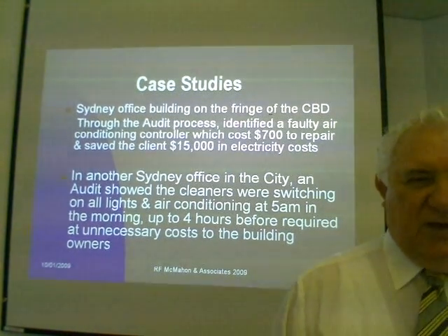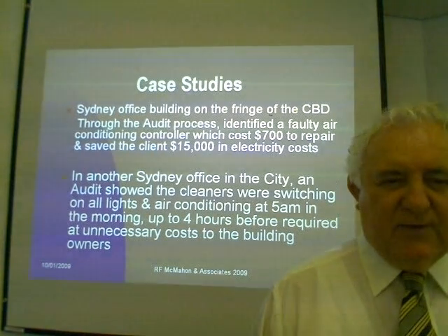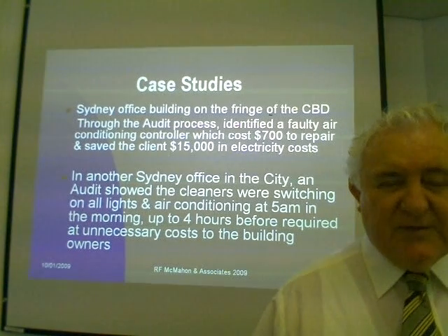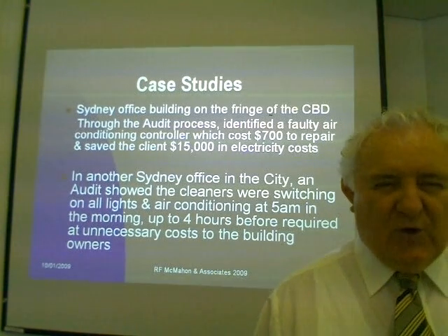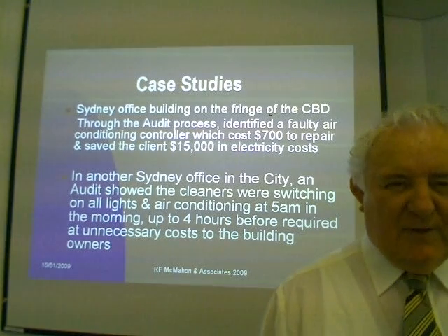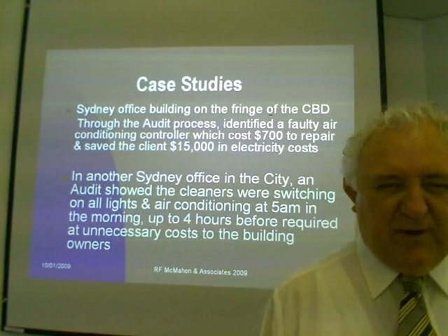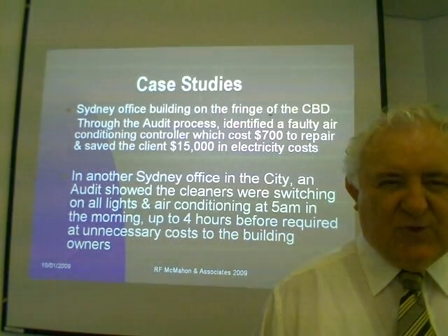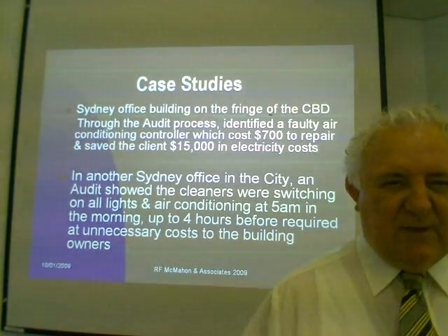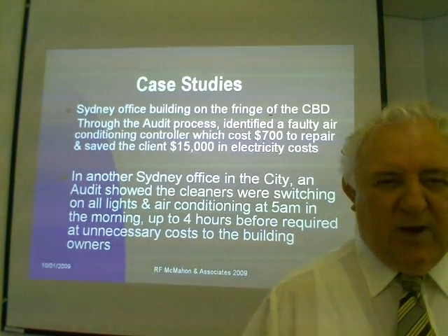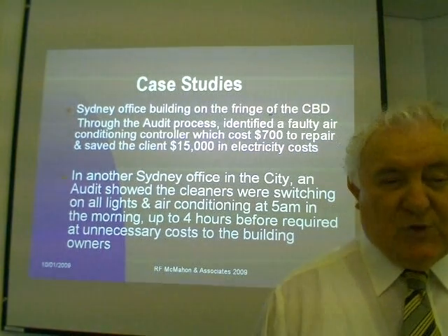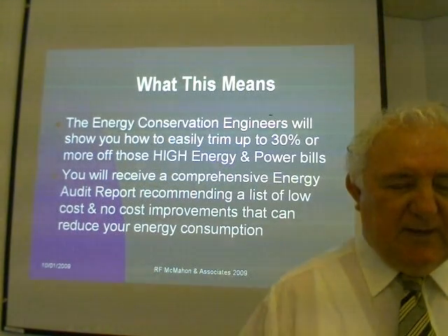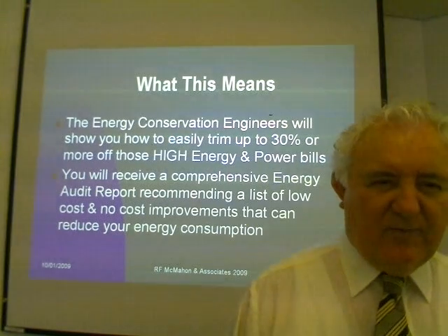In another case, we had an audit done, and the client wasn't aware of this, but we noticed that the load was coming on early in the morning at 5 when the people didn't start work till 9. So we had a look at that, and we found the cleaners were switching all the air conditioning and lights on at 5 o'clock in the morning, so they were running 3 or 4 hours in the morning when they were not required. That was costing the client a lot of money. The client was able to adjust that and save a substantial amount of money.